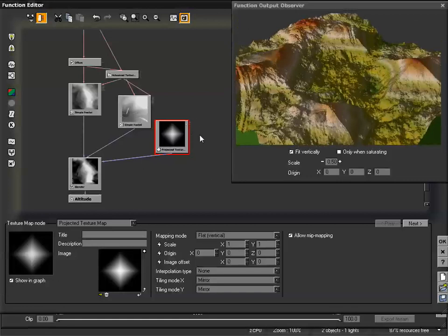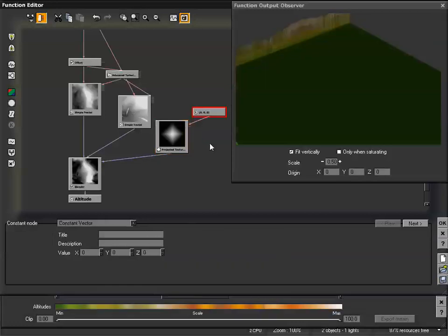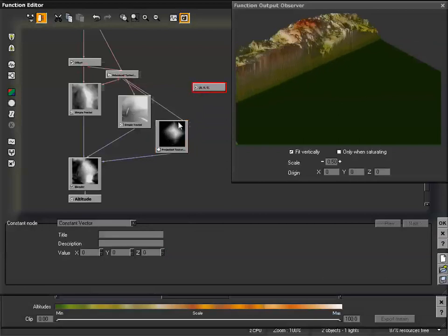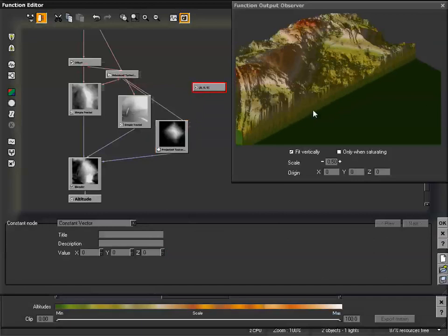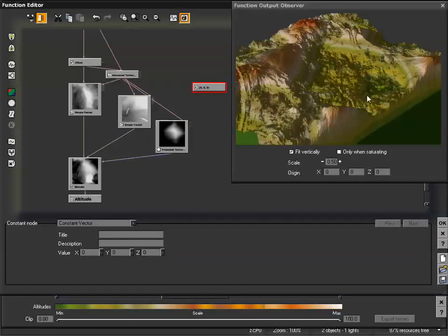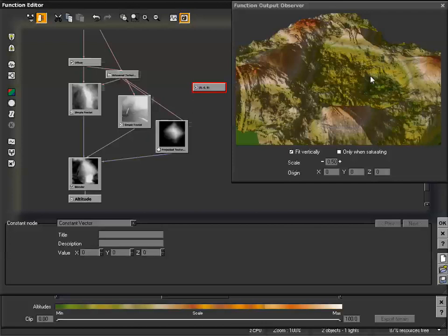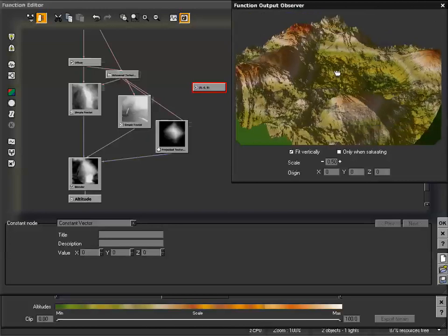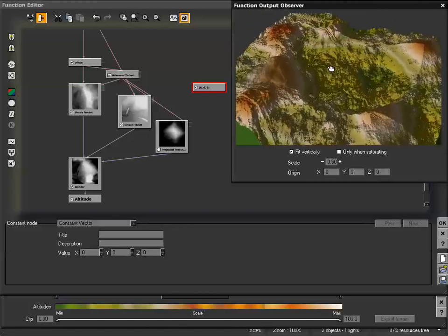And another thing we can do is actually manipulate our image maps with the Turbulence node the same way we've manipulated our other options. And we can do that by using the origin. So I'm going to extract our origin parameter. And now we have this constant node, but I'm going to disconnect from there and just connect to the Turbulence node we already have. And now we can see our image is being altered and distorted. And if we also take a look at the output observer and actually see the effects of that, we can see a nice bit of twisting within our image and what's being calculated.